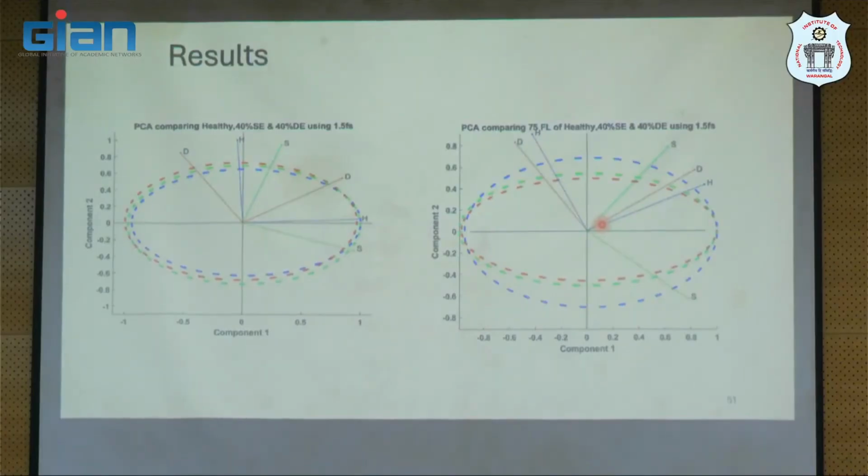For our application, since I am only using a two-dimensional feature vector, alpha and beta axis currents, it is very much simplified, and that seems to be giving us a trend in classifying whether the system is healthy or faulty. So this is the idea of applying principal component analysis to the given data set to segregate between a healthy condition and a faulty condition.